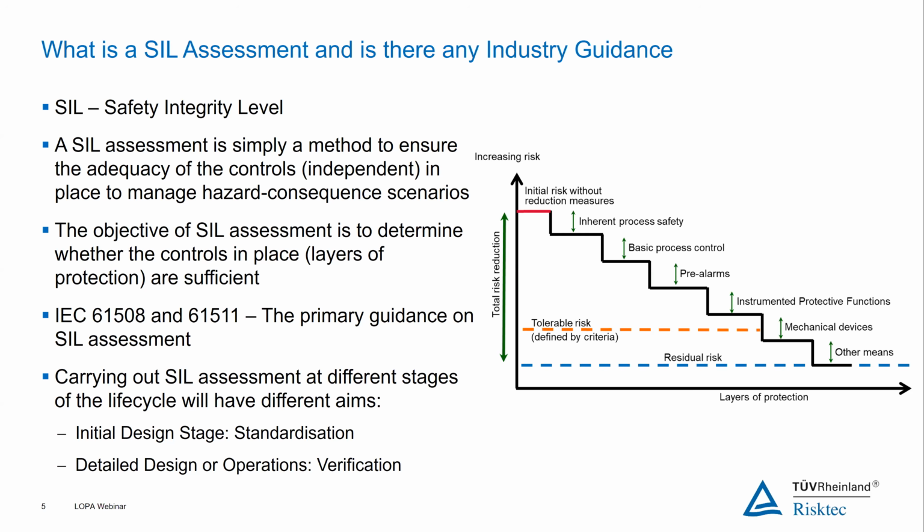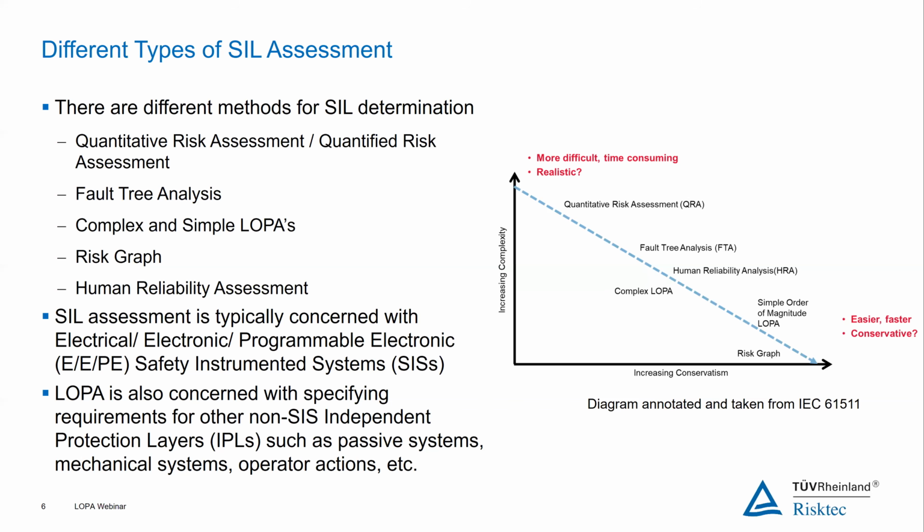One other key thing to note is that a SIL assessment isn't necessarily something you're going to carry out and never look at again. You may carry out various SIL assessments within the life cycle of a facility or an operation, and at different stages of the life cycle, these studies may have different aims and objectives. If you're carrying it out for the first time, you may be looking to standardize the controls you have in place and the assessment of them. And this could be the case if you're carrying out some sort of modification to the facility as well.